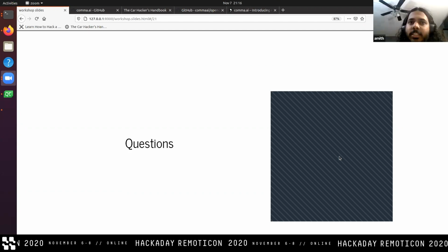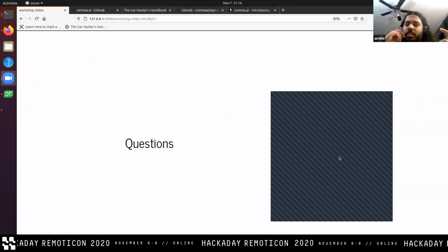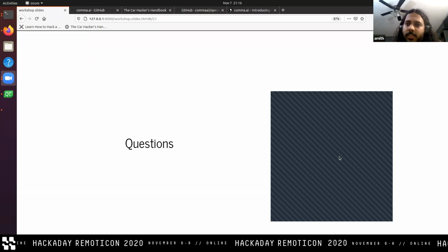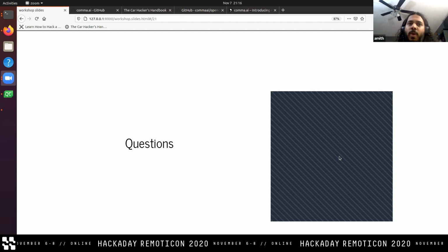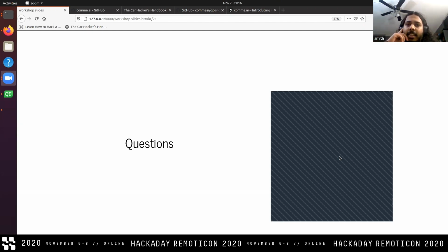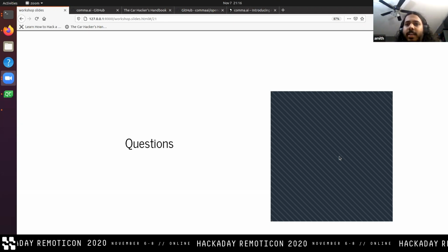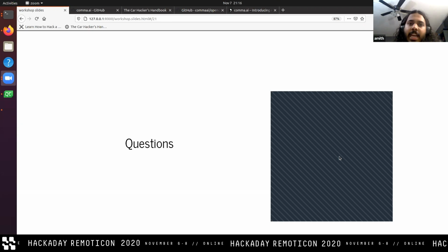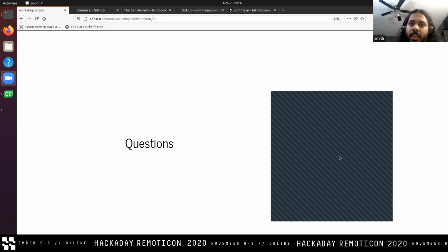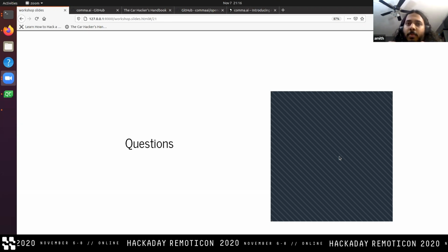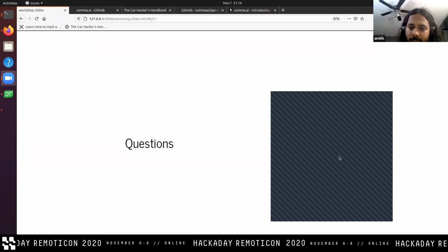One thing I saw in the Car Hacker's Handbook is that they pull out old parts from wrecked cars. Especially if your car's popular, you might be able to find salvage components and run them independently, test on isolated components, hook them up to power and see what they send. And you can input something to it. They cover it more in the Car Hacker's Handbook, but that's something you guys can look into if you're trying to do something more intrusive and you don't want to break a vehicle, and you just want to mess around with something simple.